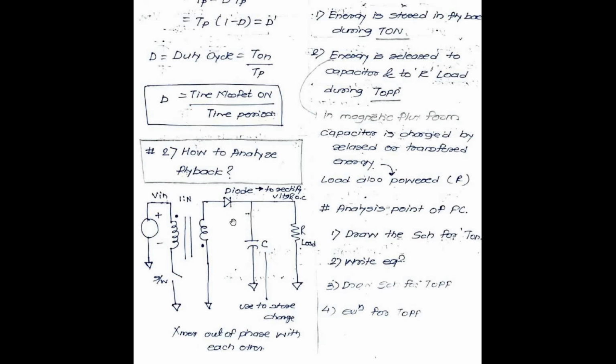For turning on the diode, the anode should be positive and the cathode should be negative. Actually, it is not exactly like that. The anode potential, note it down, should be greater than the cathode potential. At the time of BTech I was considering that anode should be positive and cathode negative, but it is not like that. The anode potential should be higher than your cathode potential.